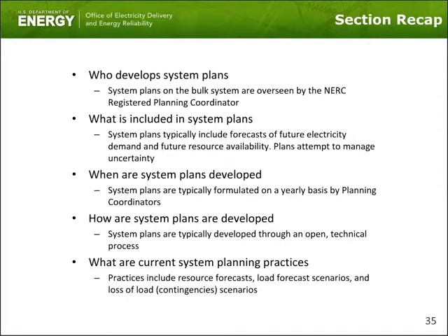This is different from variable generation resources, such as renewables, whose generation capacity may vary over the period of a day due to the prevailing weather conditions. For future system plans, variable generation resources are typically derated from their full capacity output to accommodate the variability of their output. For example, if you have a 100 megawatt wind facility in a future system plan, it may only be planning for 13 megawatts of that output.